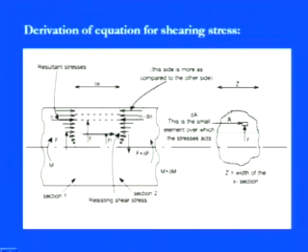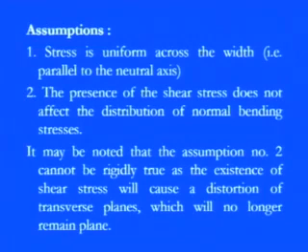So, now with this particular width of the cross section and with this dA area of this small element and with these stress components, from the left hand side the sigma, from the right hand side the sigma plus delta sigma, and under all these forces, the shearing forces and the sagging moments, this object is in equilibrium. So, now our main analysis will come: what will be the resultant bending stresses and what will be the resultant shearing stresses. To calculate those, and to put the relation between those things, certain assumptions are always needed to avoid complication in the system.